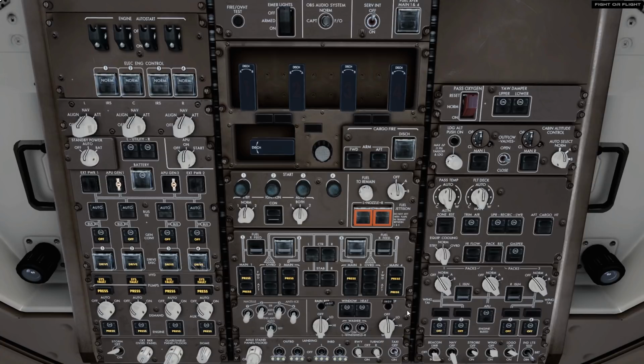Next, we'll make our way up the right hand column. Engine bleed air is on with no sysfault lights. APU bleed is on with no valve light. Left and right isolation switches are both on, as we can see from the illuminated flow bar.